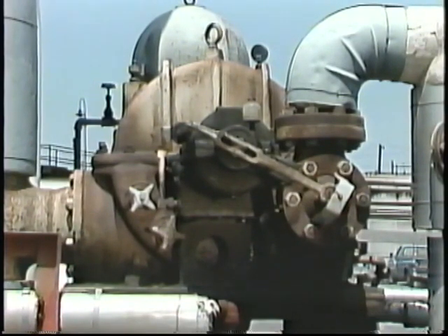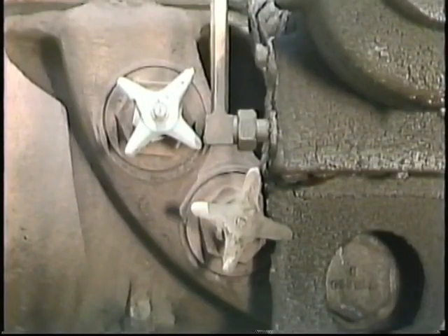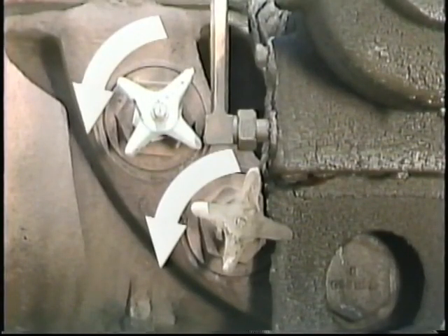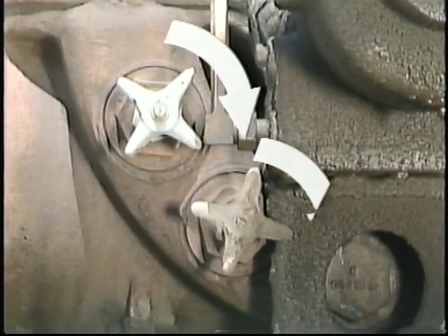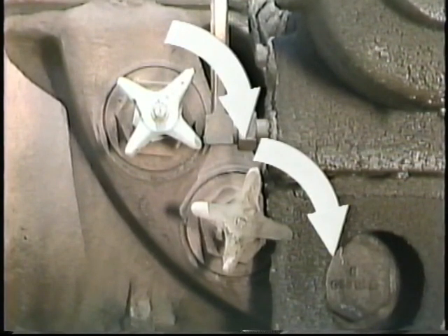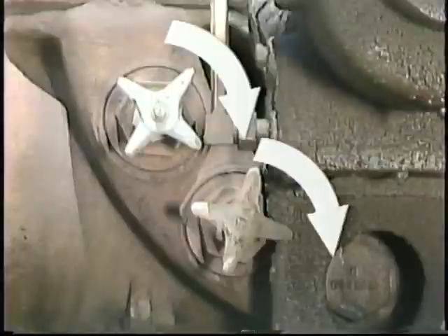If your turbine is equipped with hand valves, you may be able to use them to eliminate the hunting. How you would use these valves depends on whether the turbine is operating under a high load or under a low load. For high load, you'll need to open additional hand valves slowly, one at a time, until the speed is steady and the governor has regained control. For low load, you'll need to slowly close additional hand valves one at a time until the governor regains control and the speed remains steady.